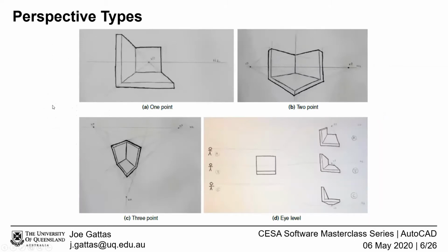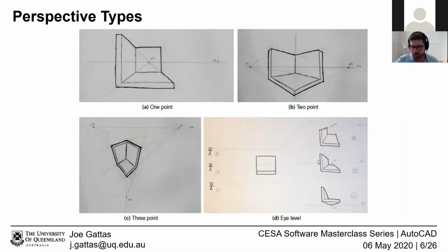But then outside projections, there are many perspective types, and for sketching, often these are useful as well because they give you a more natural feeling for a structure. And 1-point, 2-point, and 3-point perspective types are the conventional ones, but 1 and 2 are probably the main ones. 3, it's getting pretty advanced at that stage. And conceptually, you can consider these as different eye levels, giving you a different insight into angles in the structure, or angles when you look at a particular structure.